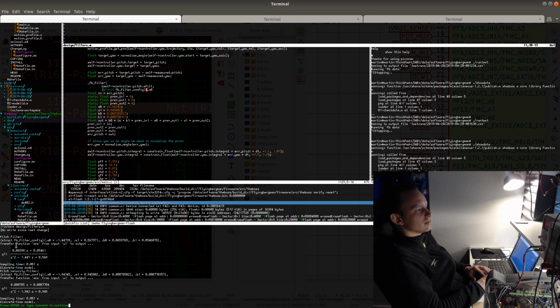You can see here, this is the discrete time transfer function, and the coefficients are directly the values for the numerator and denominator. The B values are for the previous inputs, and the A values are for previous outputs. And then you just solve this.